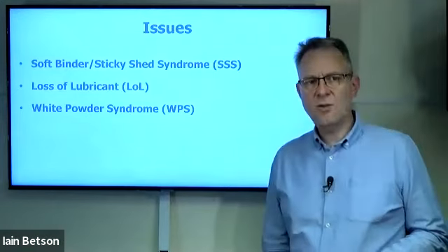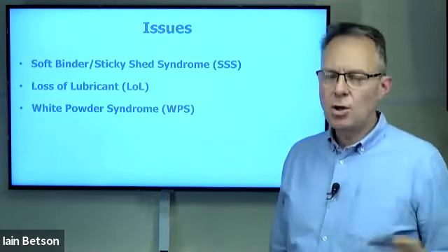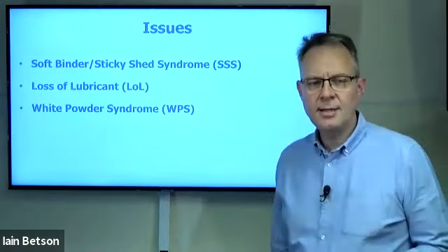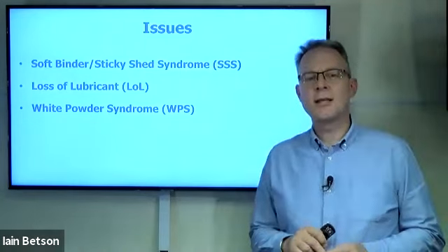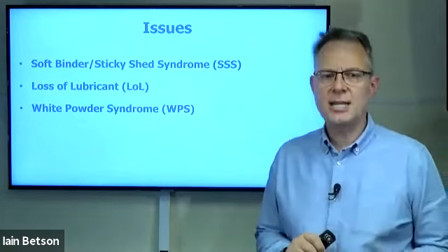Issues: soft binder, sticky shed syndrome, loss of lubricant, and indeed white powder syndrome. Soft binder and sticky shed syndrome are related, and they are something that can afflict all tapes, although some tapes are more susceptible than others. Everybody talks about the good old Ampex 456 in the 1970s, allegedly that they had a duff batch of binder, or the binder they particularly used was susceptible to sticky shed syndrome.